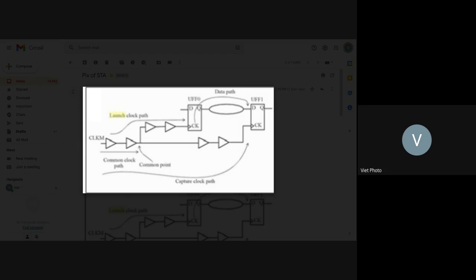That's first. The second is, because you also have a wire delay here, if you just do 2 cells here, so there's no wire delay, then this path is still shorter than this one, right? So that means when they insert, it will insert in a way that it adds 1 in here and 1 goes out here and goes back, so that it balances not only the cell stages but also the wire length.